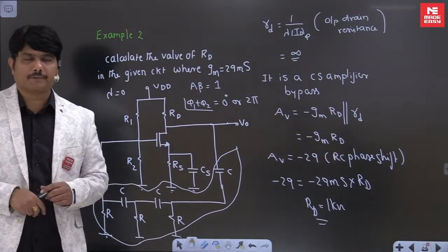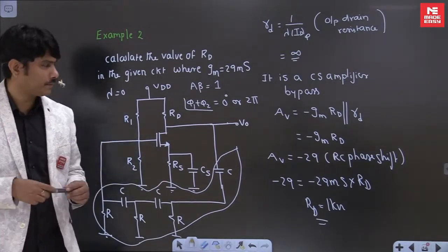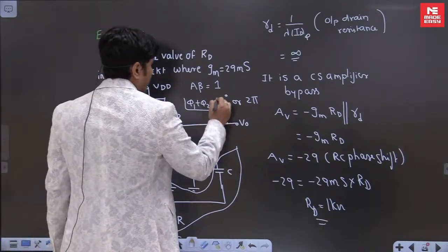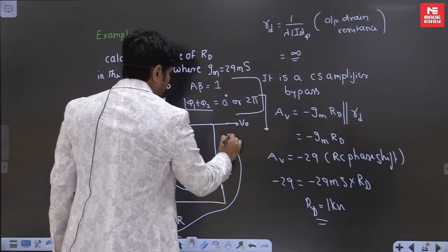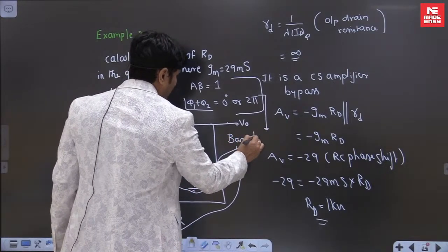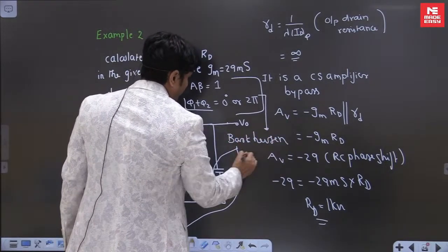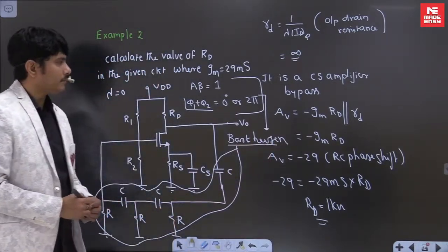We are preparing some 180 plus 180, it becomes 360. So the phase is getting balanced. So it is a positive feedback system. These two criteria are very important for designing the oscillator. This is called the Barkhausen Criteria.